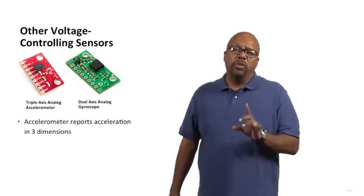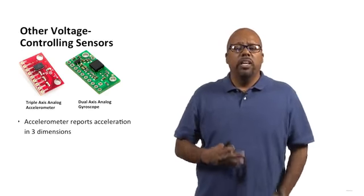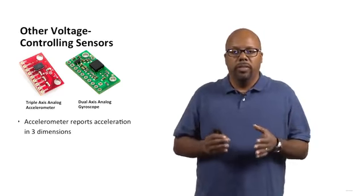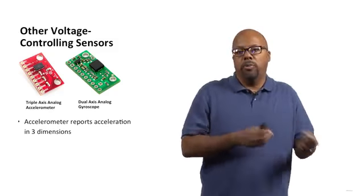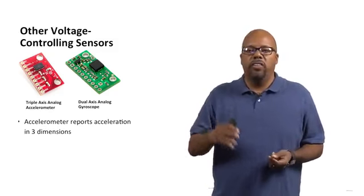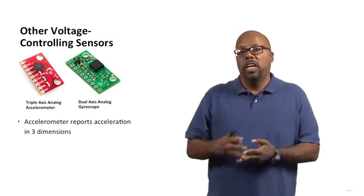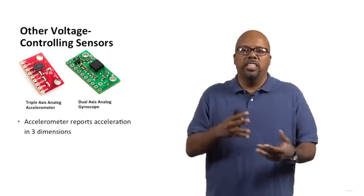So you can measure your acceleration in each axis and tell what its orientation is. So that is a voltage controlling sensor. It has those holes on the side of that little board. You solder pins onto those, what's called a breakaway board. Then you can wire those pins into the Arduino and sense the voltage on those pins. There are several of them, but there's one that's X, one that's Y, one that's Z. Those are the signals of interest. And you can wire those into the analog input of the Arduino and tell what the acceleration is in each axis.